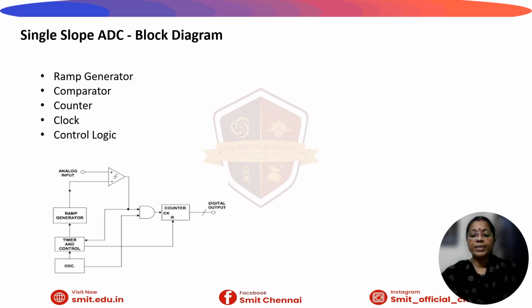A comparator continuously compares the ramping voltage against the analog input voltage. While the ramp voltage is lower than the input voltage, the counter continues to count. The exact moment the ramp voltage reaches the same level as the input voltage, the comparator switches states. This triggers the switch to stop the counter. The final value displayed on the counter is the equivalent digital output for the input analog voltage.